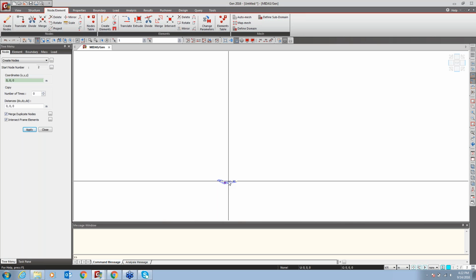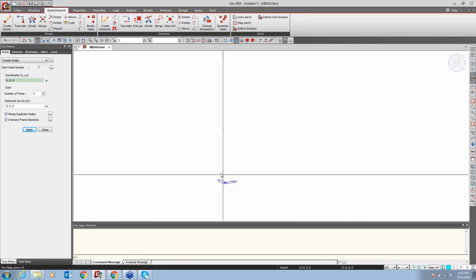So it depends on the person and their methodology. You have to be careful: if your draftsmen are good, or if you know how to generate the proper center line plan for the import function, then you can use AutoCAD DXF. It is actually the easiest method, but you have to be careful about the joints between two lines, or beam column joints, or these things.